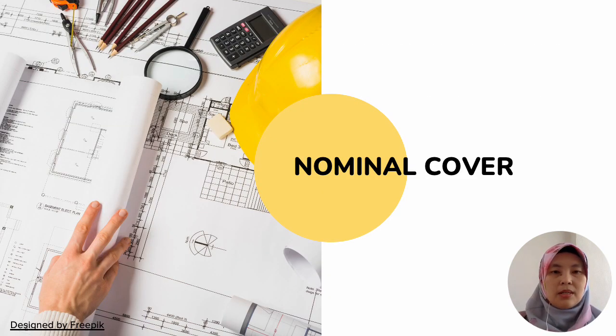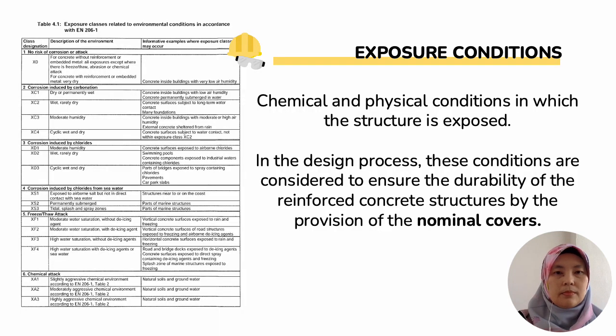So this will be the last one for this topic, which is on the nominal cover. Basically, this nominal cover will depend on the exposure conditions, which are the chemical and physical conditions in which the structure is exposed. In the design process, these conditions are considered to ensure the durability of the reinforced concrete structure by the provision of the nominal covers.